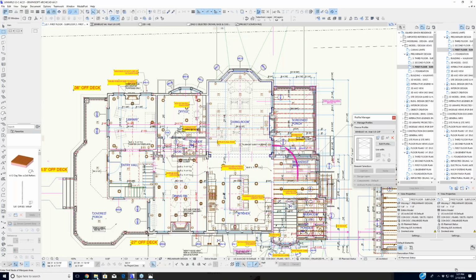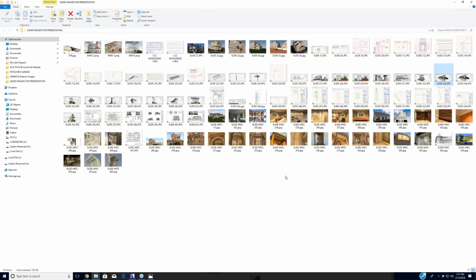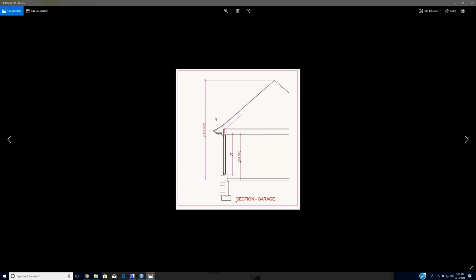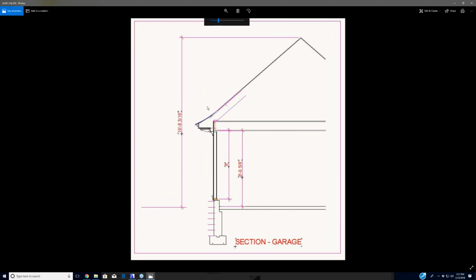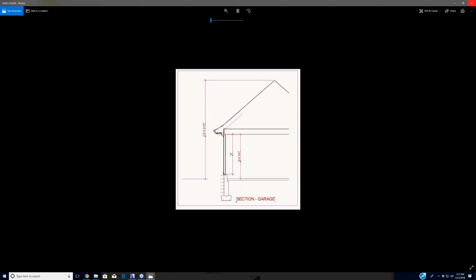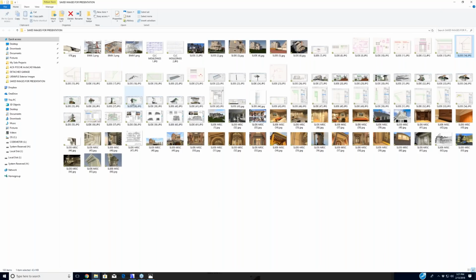The most important thing with a model, and I'm going to pull up another drawing, is before you get started at all with a model, you have to really understand the cross section. So this happened to be a detached garage, but you can see here, that is a screenshot of my desktop, 100% 2D drawing. That's all it is. I know that I want a certain roof pitch, that this is going to flare. A 2x10 is going to sit on a sill plate. So I'll model either existing or new what I truly want this to look like. Then start modeling. But I don't do any modeling until I really understand what it is that I'm trying to achieve for the final.